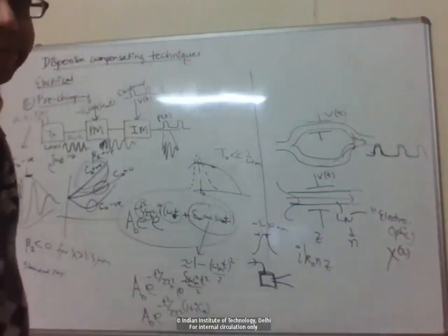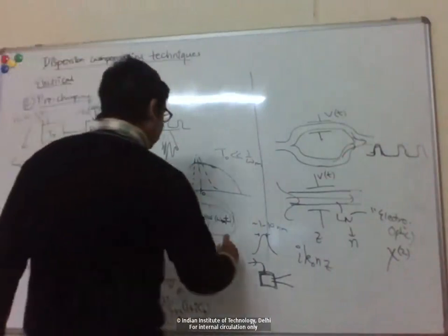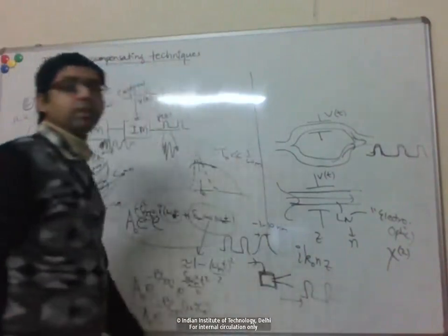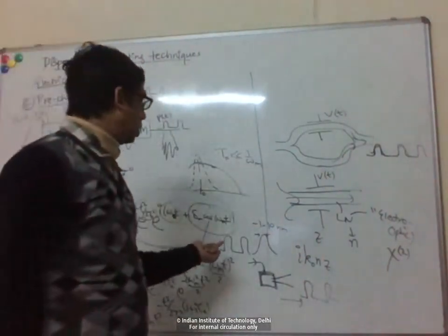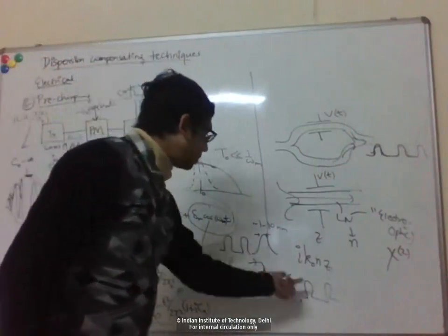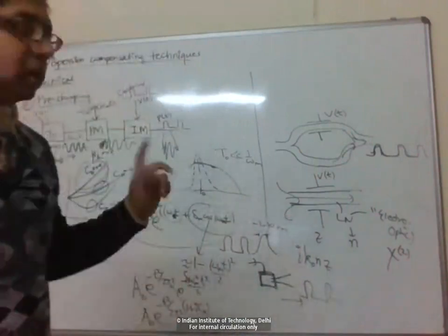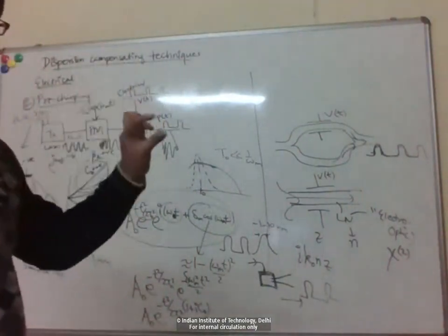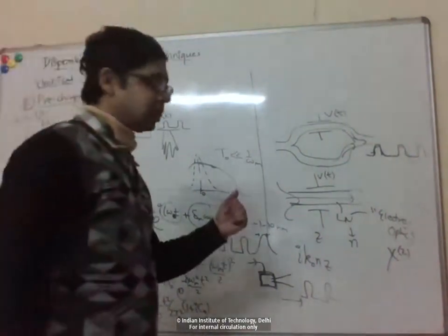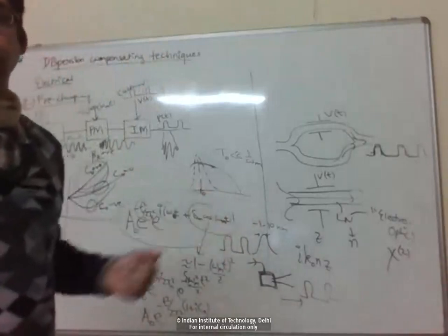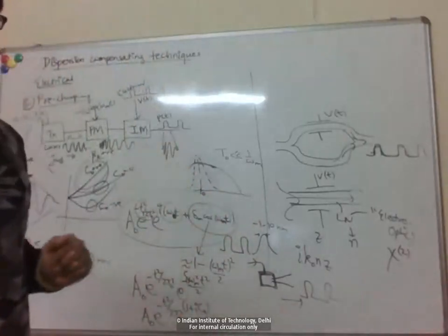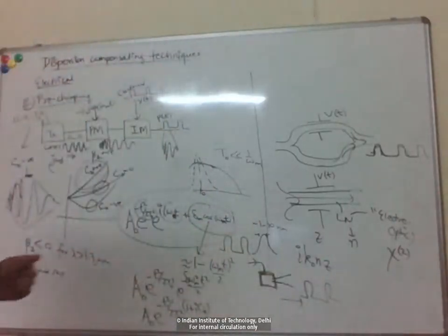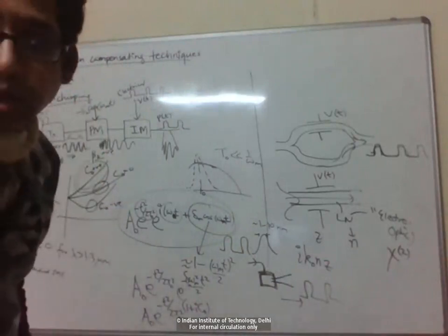By switching the current on and off, the optical power will turn on and off. So with incoherent sources, you can use the simplest on-off keying or intensity modulation, but you cannot use coherent modulation techniques which encode information in the phase or frequency. Because for incoherent sources, phase and frequency are not well defined, it's randomly jumping out of phase. But the intensity or power you can still use. So that's what's done.